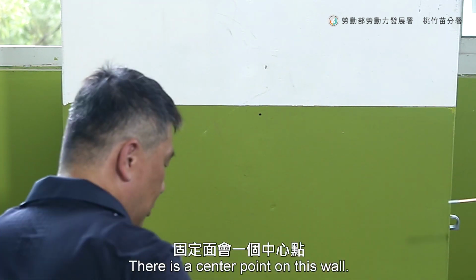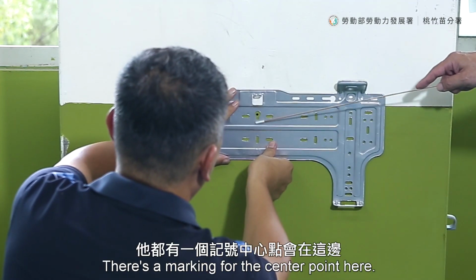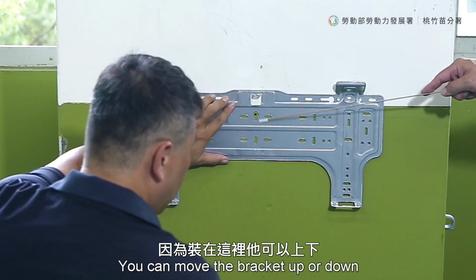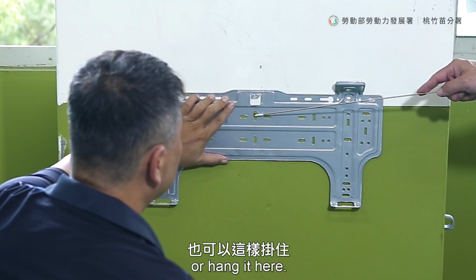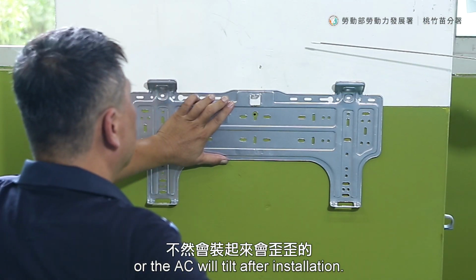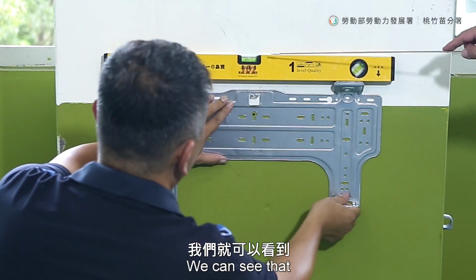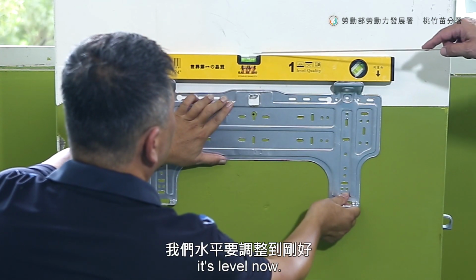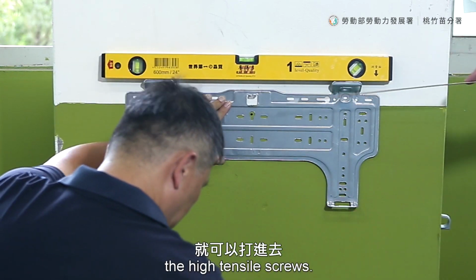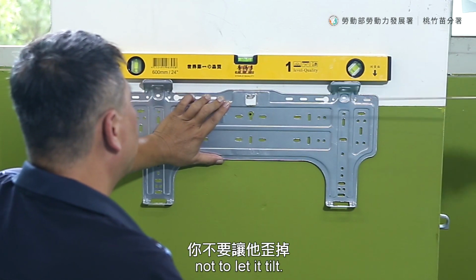There's a center point on this wall. You must align the bracket with the center point. There's a marking for the center point here. You can move the bracket up or down or hang it here. Remember, the bracket must be level or the AC will tilt after installation. So we'll use a long level to secure it like this. You can see that it's level now. Now we can tighten the high tensile screws. Always be careful. Do not let it tilt.